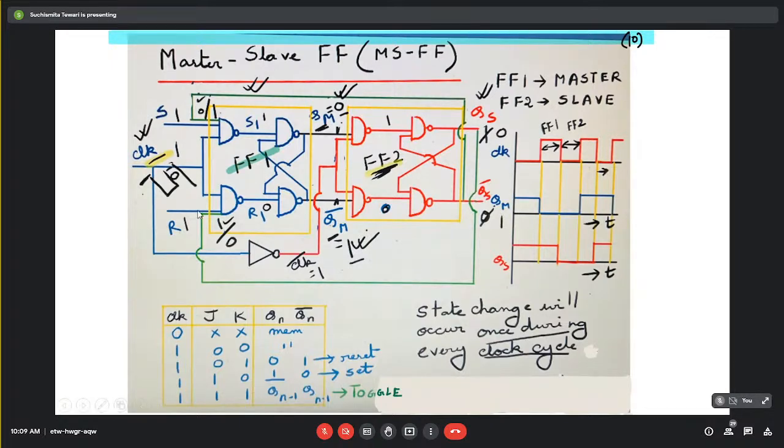More number of components means more amount of delay. In each case, the signal from this input has to go through this flip-flop and this flip-flop as well. So the delay is increasing. And also another additional gate, this NOT gate, is coming over here. So from here to here, it will suffer some amount of delay, because no reflection of input to output is instantaneous. Some amount of delay, and here we are not considering the wire delay.